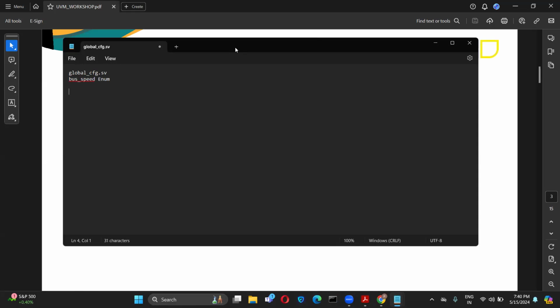Yeah, correct. So basically, as I said, from the test bench we are trying to provide the stimulus, different kinds of inputs. The project in real time is not as simple as we think, like a simple adder or subtractor. These are the simple things we work on to learn the concepts. But in real time, the projects are very complex, right? So in that case, how does the stimulus get generated? Will you sit and write each and every stimulus on your own? It's not possible, right? Then this randomization comes into the picture.